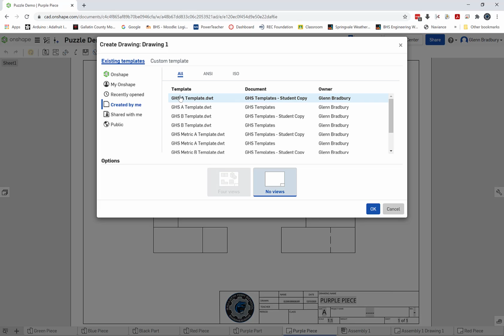That gives a good idea of what this object would actually look like. Once you have your 3 views there, the last thing to do is double check that your front view is the best front view according to the three rules of front views. First off, does it have the longest dimension? In this case, yes, it does. Second, does it show the best detail or most detail? And you can see realistically it's probably as good as it's going to get. And then lastly, does it have the fewest number of hidden lines in all of the views? And of course we only have 1. And looking at this object, I know from experience that that's probably the best you can get.